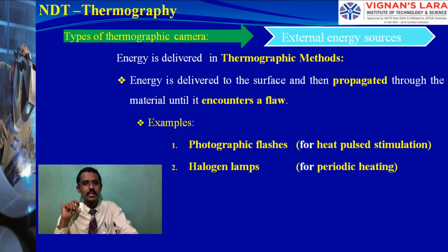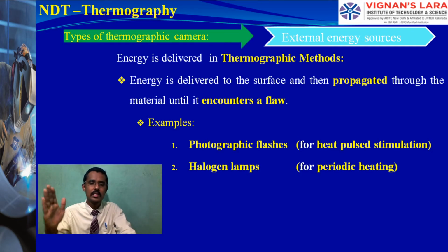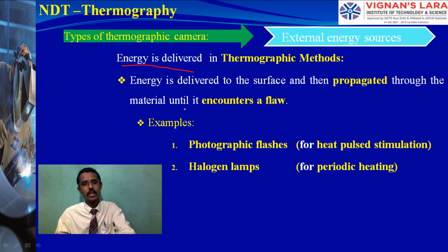Out of all these things, somehow a common source of energy is there. The energy is delivered in the thermographic methods. Energy is delivered to the source and then propagated through the material until it encounters a flaw.